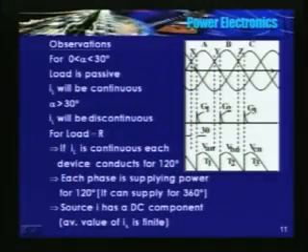I will encourage you to go back to your room and draw the voltage waveform across the blocking thyristor. See, at point X, the instantaneous value of VAN is the same as VCN. So the voltage across the thyristor is 0.